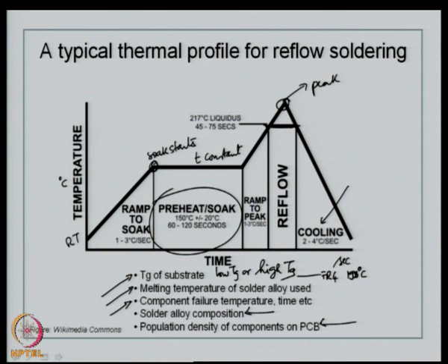So, this is the maximum generally as a guideline, as a rule of thumb. You can take it that a double sided board assembly can undergo thermal shock through soldering process twice, typically dual reflow, plus a few components that have to be mounted by manual soldering.